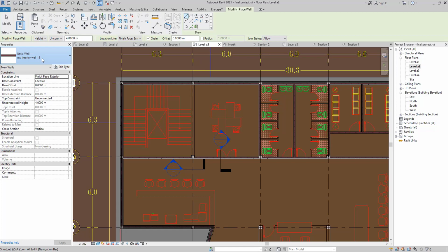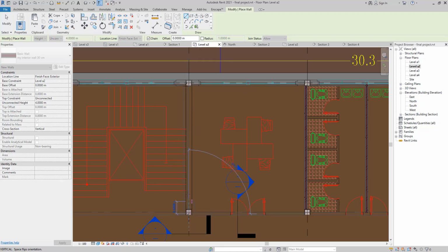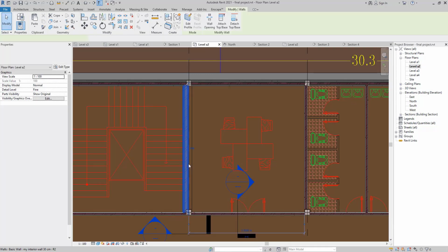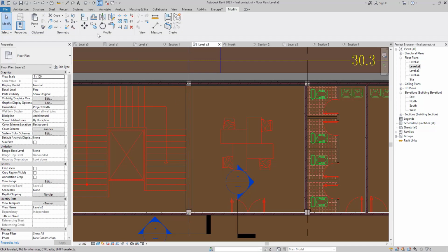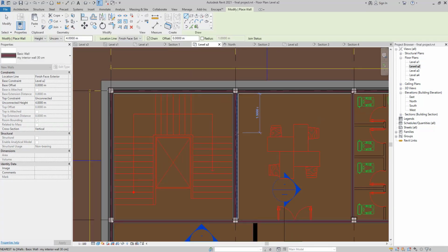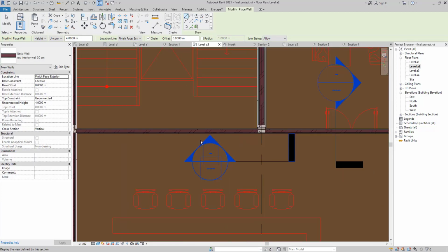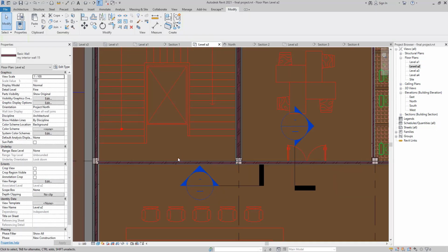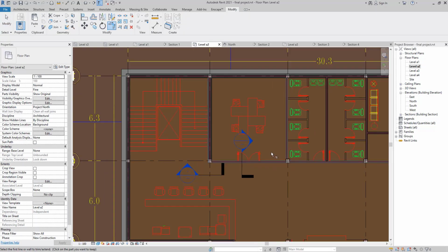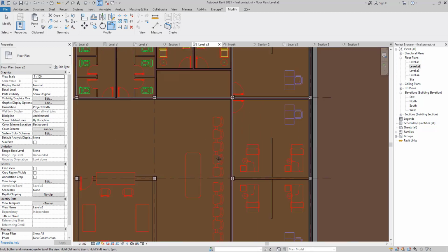Then we will go to the wall 30 centimeter interior, and we are going to draft our wall here as well by picking the wall. Because we changed the location line, so it changed. We need to draft it from this way, and we are using our interior 30 centimeter, so everything looks fine. This wall is supposed to continue until here because it's our stair box.